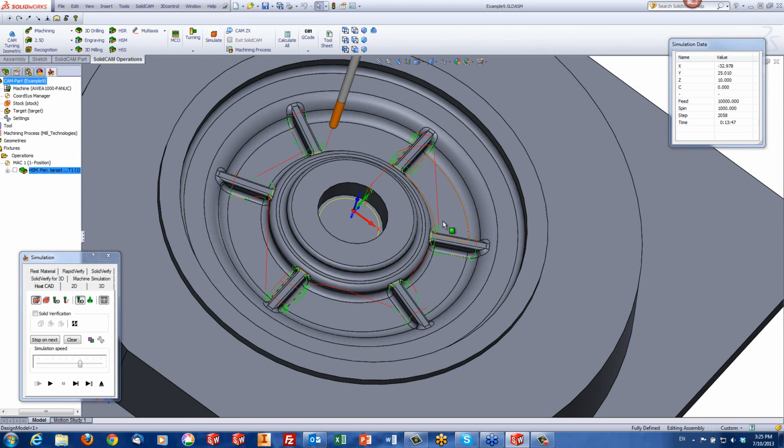So, in essence, when it gets to this point, it looks at its second contact point area, and since this radius is smaller than this radius over here, the bitangency angle is practically zero. Therefore, it did not create a tool path. But in any case, I want it to create a tool path on this area.